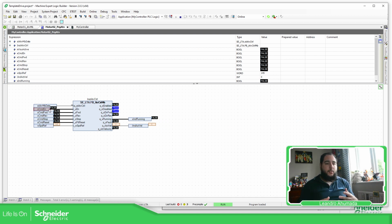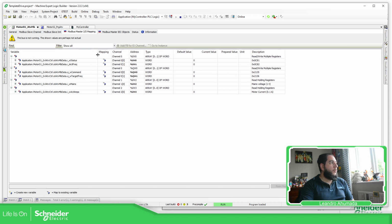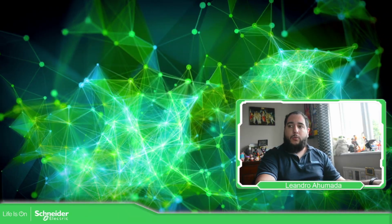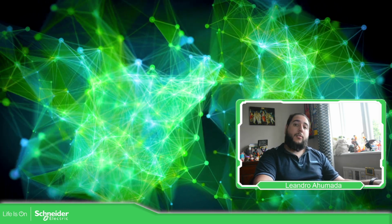Okay, so these are the different ways to control the drive using this template. I believe it's going to be much easier, so you don't need to make any intervention on the actual device that you added. Okay, instead of linking all the variables, this is all done for you, so you don't need to do any extra work here. So this is it for the template of how to control an Altivar drive using Modbus serial.